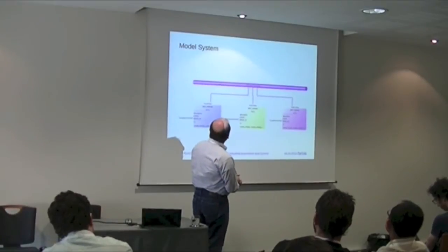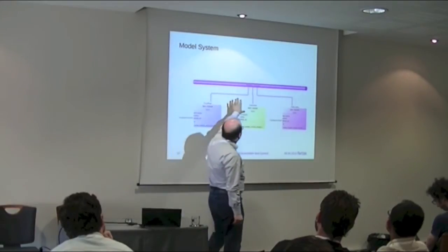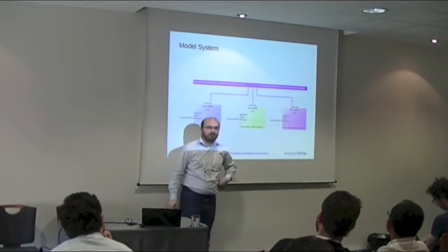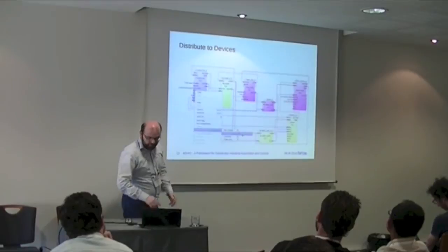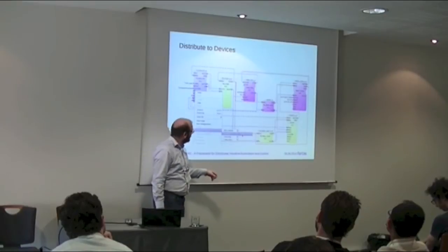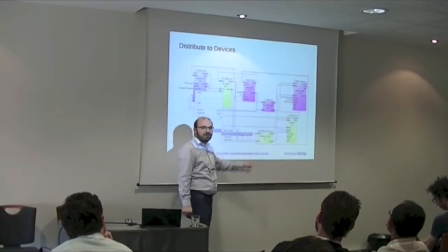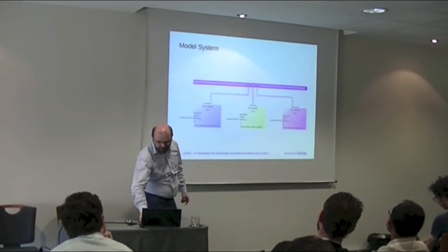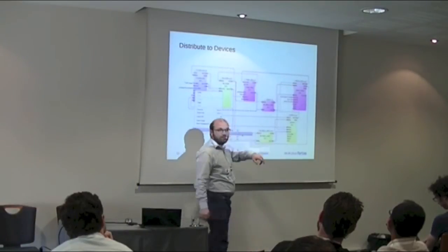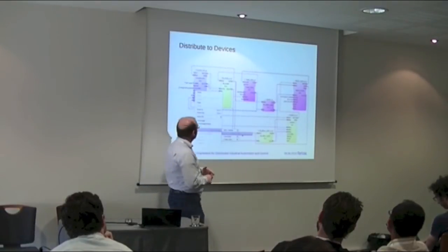So in this case, I dedicated a device for the HMI, a device for the controller, and for the simulation, I dedicated a third device. And now I can assign my function blocks to the different devices. You already see I have done this for all these function blocks because now they have a color, so they match the color of the devices here. And you also see these dashed lines, which means these are connections that are now broken. So these are connections that are going over the network.